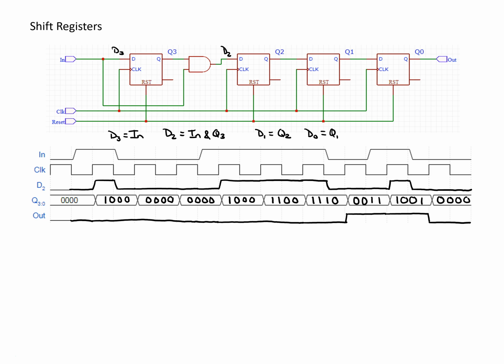We can see that this somewhat behaves like a shift register, but it's a little bit different in how it deals with an input of 1. So instead of shifting out an input of 1 all of the time, it basically shifts out 1 fewer 1s than were in the input. So when input was high for only a single clock cycle, we didn't shift out a 1 for that. And when an input was high for 3 cycles, we only shifted out 2 of the 1s. So one way that this could be described would be to say that this shifts out 1 fewer consecutive 1s